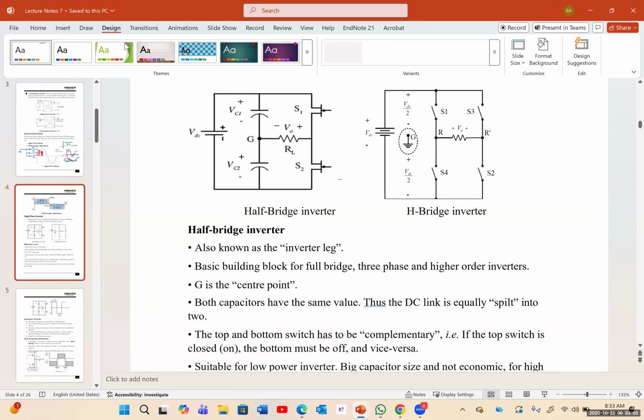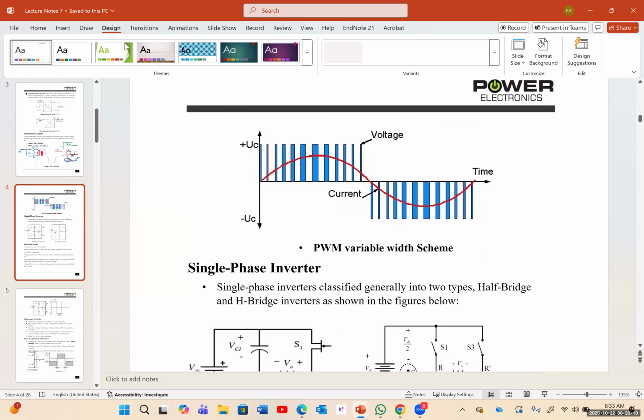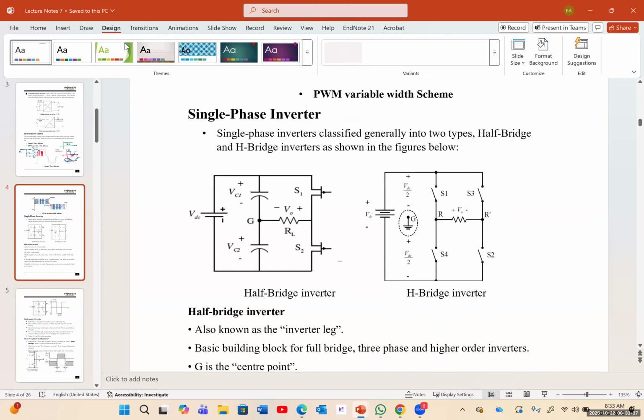You just need an op-amp to do the switching. But if you want to build a perfect sine wave, you need a sophisticated control system and a very fast switch. Okay, the previous switch, you have to switch 50 to 60 hertz, something like that. Double that, it's going to be 120 hertz. This one, it's around 200 kilohertz, megahertz. So a much faster switch, which is much more expensive, and a very precise control system to be able to build this